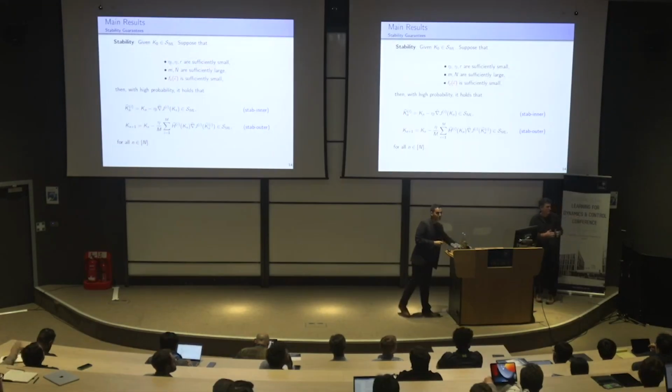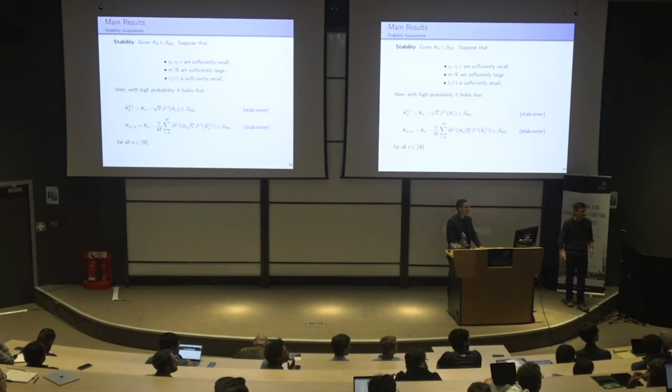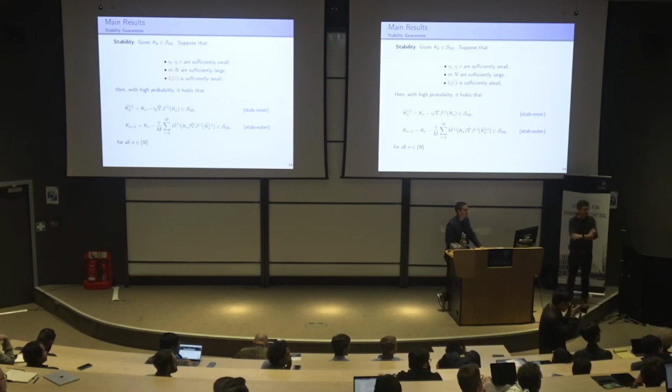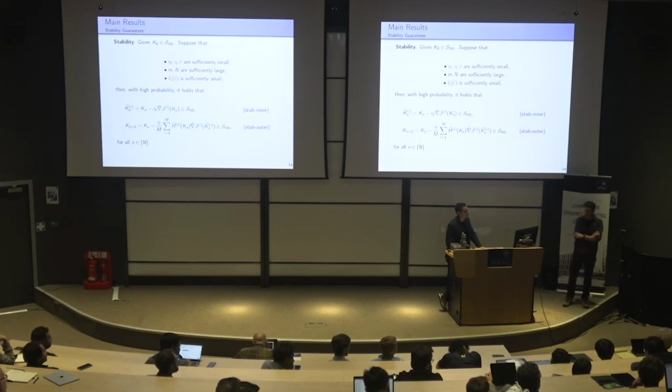Thank you. One more question. This idea of generalizing to multiple tasks is certainly an intriguing one. But the theorems that you quoted are all about the t tends to infinity versions of LQG. It seems to me that the problems you really want to solve are where there's a transient before t tends to infinity. My concern is that you are iterating among the stationary solutions of the Riccati equation in the choice of A_i.